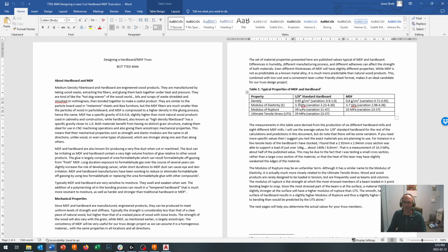And the material that we're using may have come from a different manufacturer, and you'll have to use some of our beam bending formulas and structural buckling formulas that we've talked about in class to get maybe a better estimate of the modulus of elasticity of this material, because as you can see, there is a fair bit of variation in what you might see from hardboard, anywhere from modulus of 3.2 all the way up to 4.6.